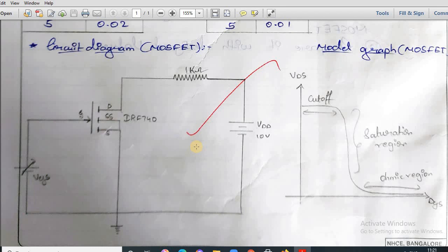One of the most unique properties of MOSFET is that the gate terminal does not draw any measurable current. The 3 terminals of MOSFET are denoted as gate, drain and source terminals. Further, these devices can also be classified into depletion type and enhancement type MOSFET depending on whether they possess a channel in their default state or not. They can also be P channel or N channel devices, as their conduction current is due to holes or electrons.